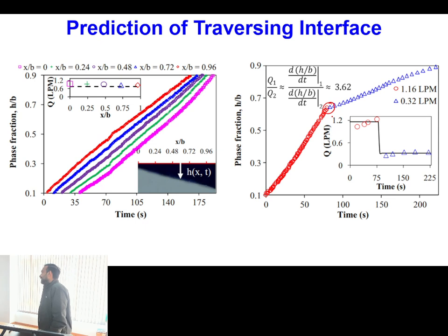Okay, in case your time scale of interface change is significantly high in comparison to the response time of the photodiode to light in photovoltaic mode, then photodiodes can also be used with the help of some more electronic circuits in photoconductive mode.